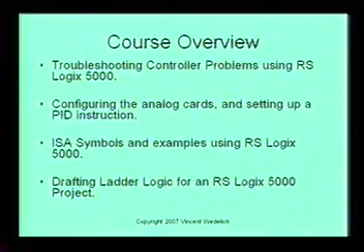And each ISA symbol is a key for you, because when you see a certain ISA symbol, you know instantly in your mind, oh, I've got so many analog ins and so many analog outs and things of that nature. Or I know that this is a pressure transmitter, and usually 90% of the time pressure transmitters are 2-wire devices as opposed to 4-wire devices. So it actually tells you in your mind how your PLC needs to be wired up.